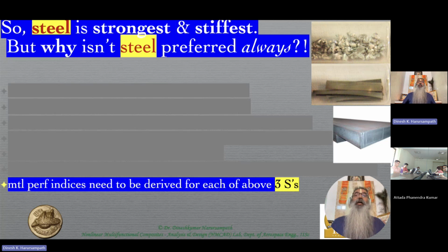I've already mentioned in passing that sigma_u by rho is the specific strength, in one of the earliest classes, the very first week, and we also saw that E by rho, the Young's modulus by the density, is the specific stiffness. But that was just taken for granted at that point, though it made some kind of logical sense. We want a clearer derivation from the point of view of structural analysis. Without going into the full details, we will see a few steps of the derivation in order to understand it, just the way Olivier introduces these concepts as well.